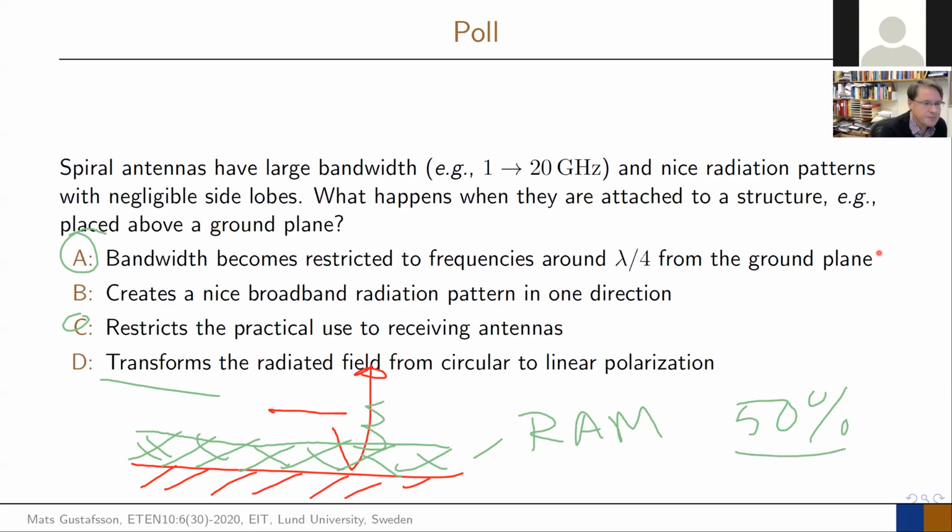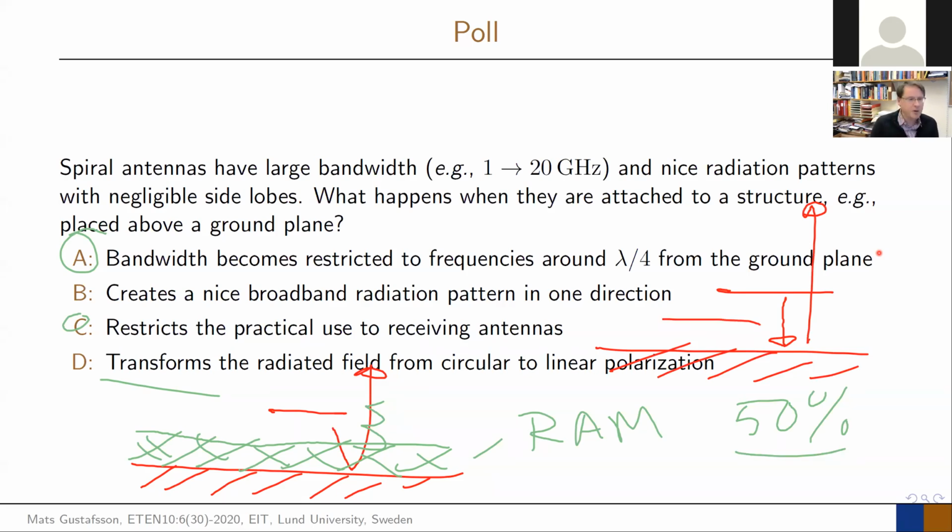Khaled? Yes. So what's happening there is that if you have your spiral here, I will draw it again. We need to end soon. Okay, now I can probably draw. So I have this one here and I have my ground plane here. What's happening here is that this one is sending out the signal that gets reflected up there. And the propagation distance to this one, now we say it's lambda over 4. Lambda is 360 degrees. So that means that this is now a 90 degrees phase shift to go down.